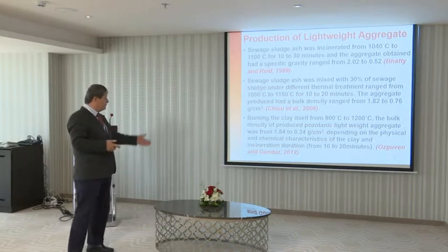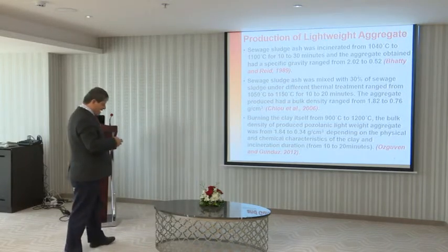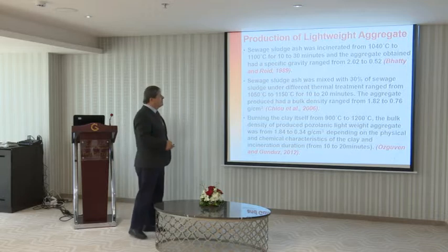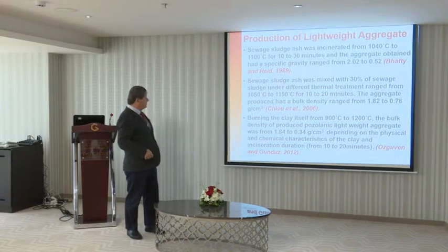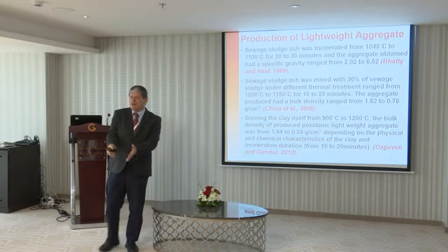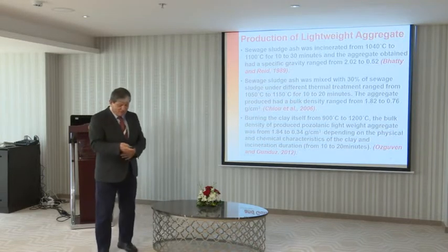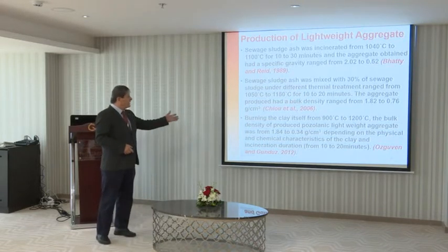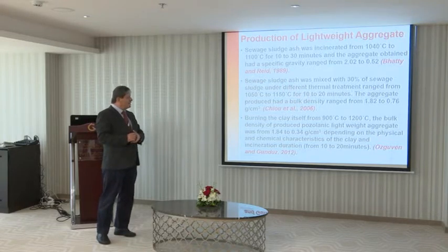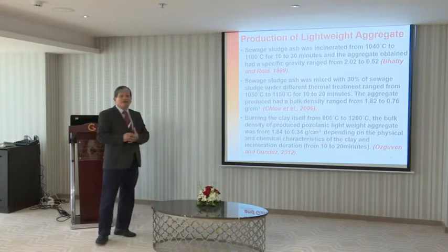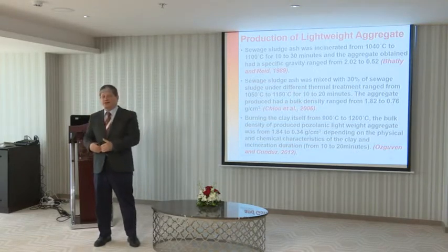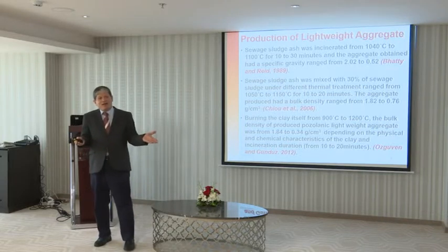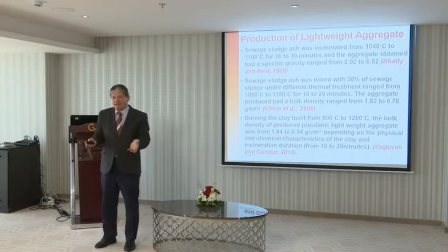But you can see some research is done, and the specific gravity, as you see, is changing in this range, or in this range, or in this range. So you can really produce a lightweight material. This is the target, with different alternatives. Clay here is an interesting material. In San Diego also we used clay because after burning, clay expands and its specific gravity reduces. And burnt clay is a kind of pozzolanic material, as we know.